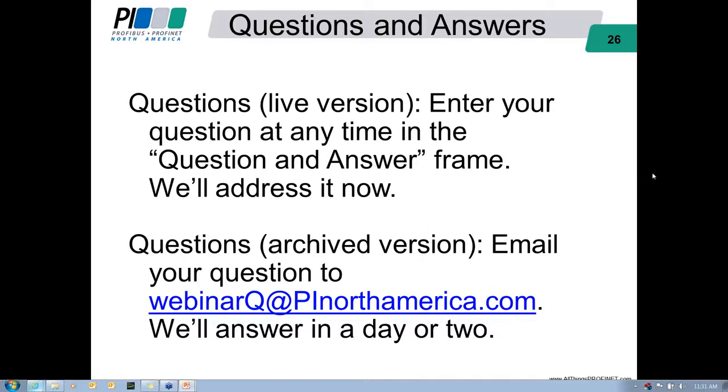Let's see what other questions we have. Is PROFIenergy ready for prime time? Yeah, I think the answer to that is yes. There are products already available for PROFIenergy. There are controllers, there are I/O blocks, there are drives, there are starters and contactors, there are Ethernet switches. All of those things are already available. Recognize that we're early on. There are not hundreds of products yet, but there's certainly a handful of products, and you could get started right away. And even if the product that you're hoping to see PROFIenergy in doesn't have it yet, the ability to add PROFIenergy to an automation device is not difficult. Typically it is just a firmware update. So really can't go wrong starting to use PROFIenergy in projects today.